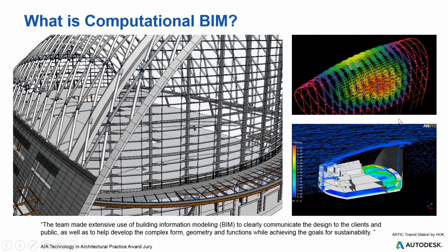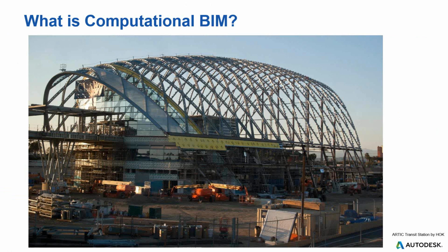So combining the geometry, extracting that out to do things like daylight analysis or computational fluid dynamics to figure out airflow, all of that was more possible because the model was not just being used to create essentially 1,000 drawings in a drawing set, but was able to carry all the way through into construction.